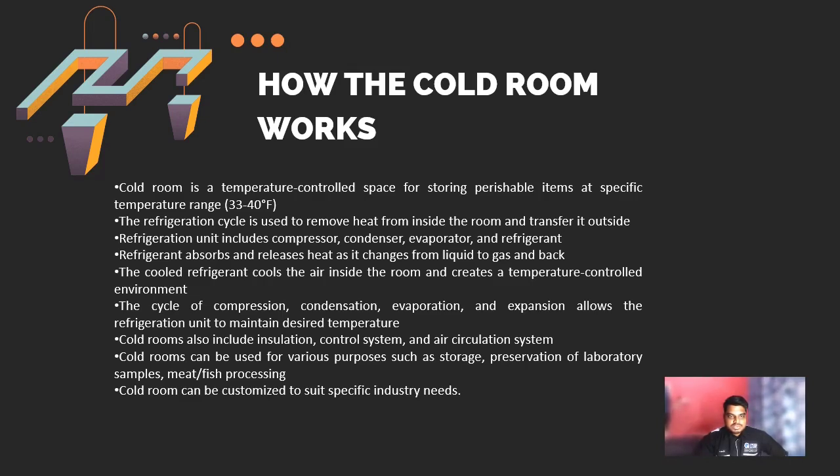Today I'm going to tell about how the cold room works. The cold room is a temperature controlled space for storing perishable items at a specific temperature range of 33 degrees to 40 degrees Fahrenheit. The refrigerant cycle is used to remove heat from inside the room and transfer it outside. The refrigerant unit includes the compressor, condenser, evaporator, and refrigerant.